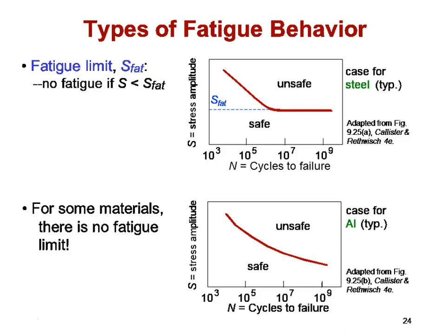That's what we call a fatigue limit. So for a material, if you keep it below a certain stress amplitude, and again, this would be specific to a given offset stress around which you're cycling, you don't have to worry about fatigue.